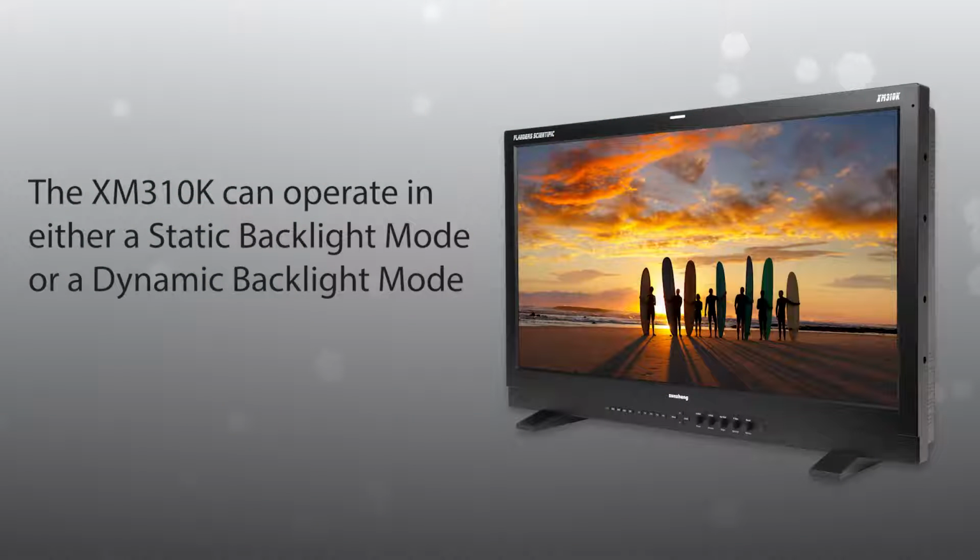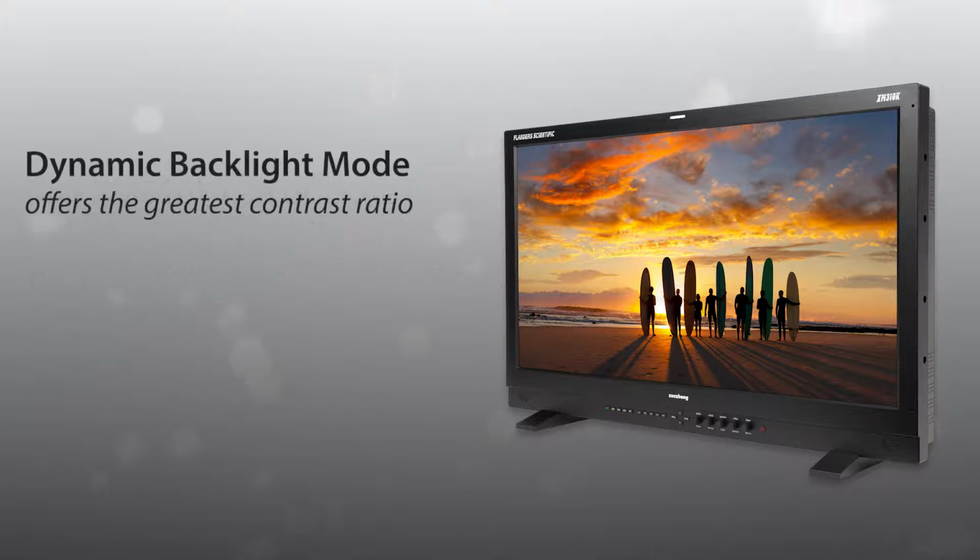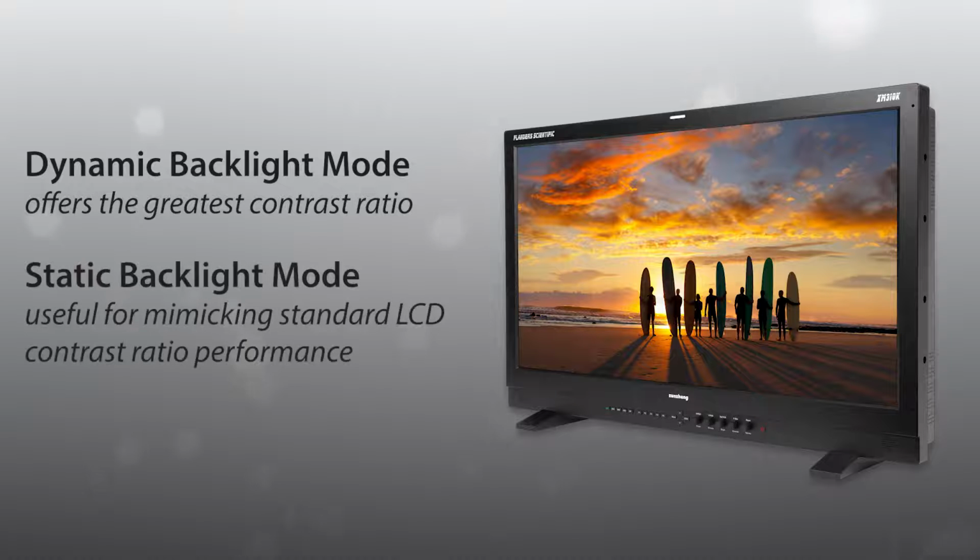The XM310K can operate in either a static backlight mode or a dynamic backlight mode. The dynamic or modulated backlight mode will give us the greatest contrast ratio, and it is our assumption that most users will utilize the XM310K in this way the majority of the time. However, for some applications, like mimicking standard LCD contrast ratio performance, it may be useful to use the monitor in a static backlight mode configuration. We'll start by calibrating the monitor in the static backlight configuration, then we'll show calibration in dynamic mode.